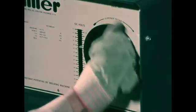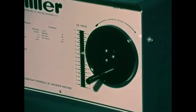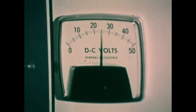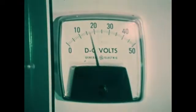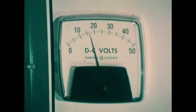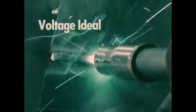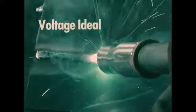The short-circuiting method is a low voltage and low amperage system. Logically, a low voltage setting is selected. Voltages over 21 volts will tend to produce spraying, or a globular metal transfer and not a short-circuiting type of metal transfer. With an open circuit voltage of 24 to 25 volts, the voltmeter indicates 17 volts during welding. This is the actual pressure or voltage under load in the circuit.